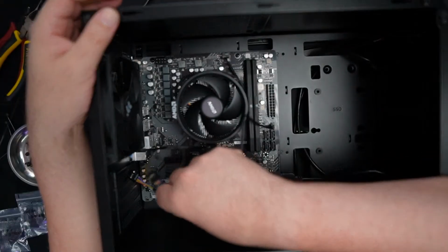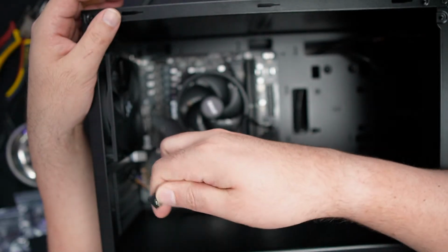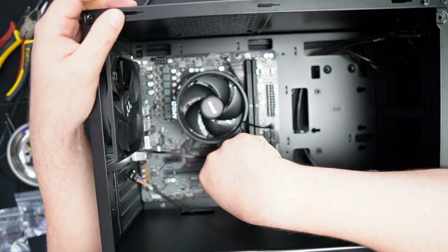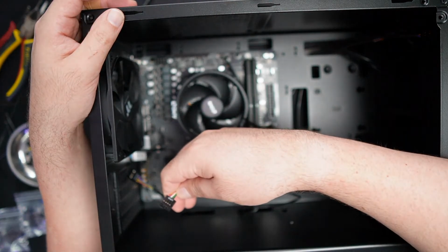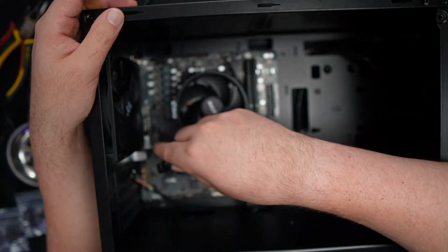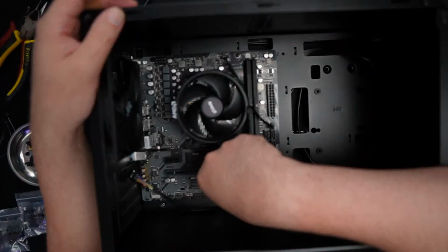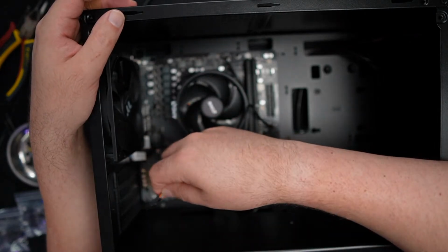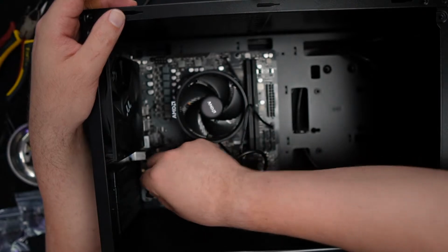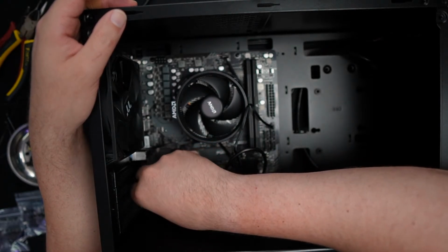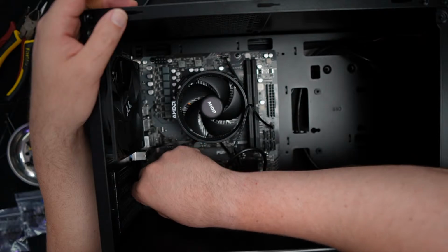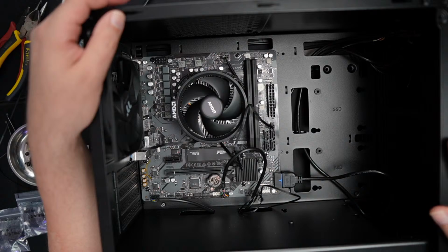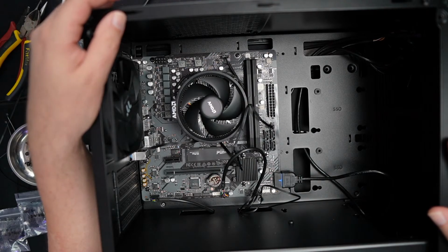And we're going to do the USB 2.0. Again, it's labeled USB, and it goes into the header that says F USB 1 for front USB 1. It could also go into F USB 2. It really doesn't matter which one you plug it into. It will work. If you have more than that on there, you just plug in the next one. HD audio, same thing. It's all blocked out, so there's only one way to plug it in. If you are pushing too hard and you're bending pins, you're obviously doing it wrong. Do not continuously do that. Flip it over, maybe you got the wrong direction.